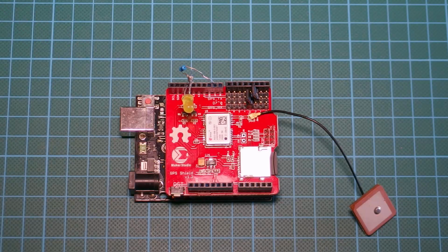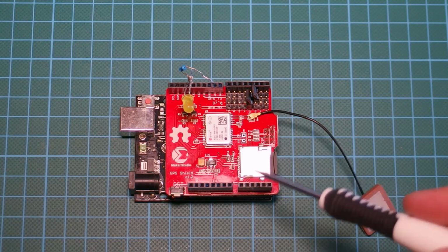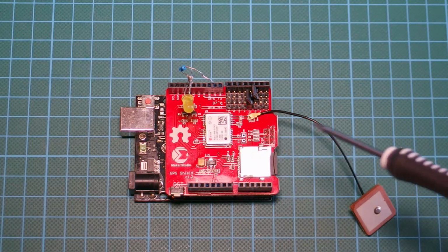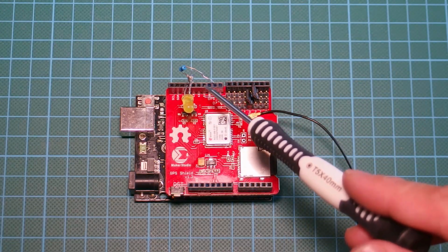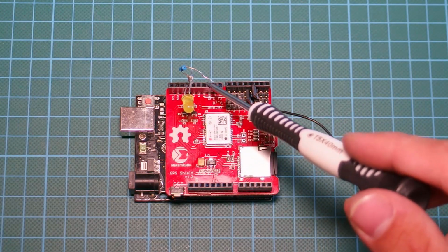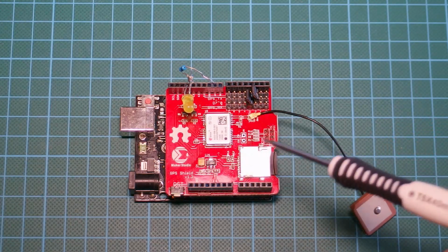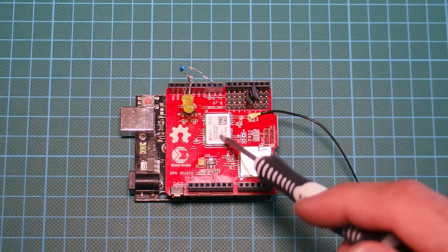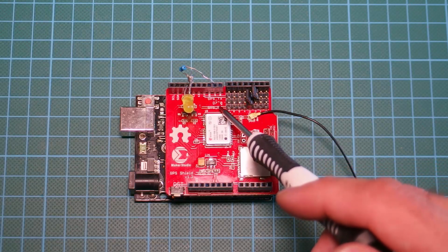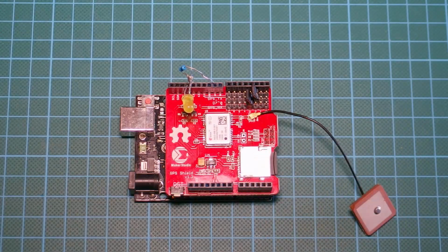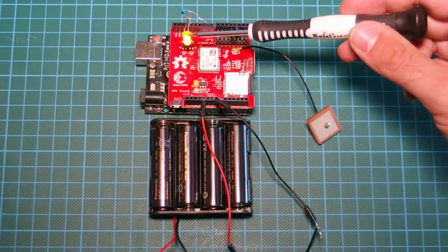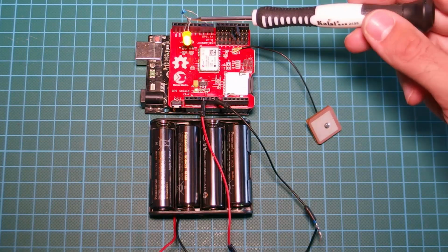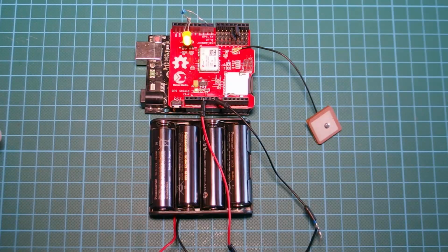Building this project is extremely simple. All we need is the GPS shield from Maker Studio, a micro SD card and of course an LED. I have connected the LED to digital pin 9 because digital pins from 13 to 10 are used by the SD card module. Digital pins 2 and 3 are used by the GPS module, so digital pin 9 is available to use for the LED. If we power on Arduino, now we can see that SD card is initialized. Okay, it works fine. Now we wait for a GPS signal fix.